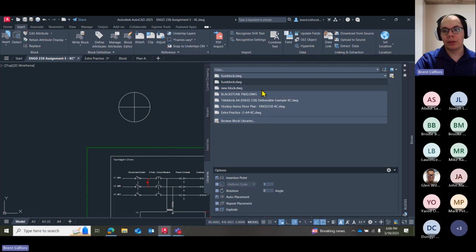Okay. So again, if I'm saving something like a resistor symbol or a capacitor, something I use very often, I can save that as a separate drawing file at the same time as defining the block. And then that can be put in a folder, and I can recall it from that folder at will. Instead of having to, say, make these different blocks on assignment 5, assignment 6, assignment 7, and then I have to remember in my head, oh yeah, where did I make that fuse symbol?